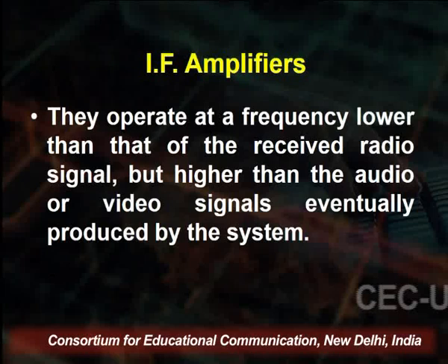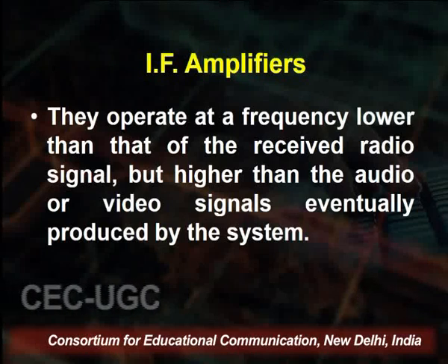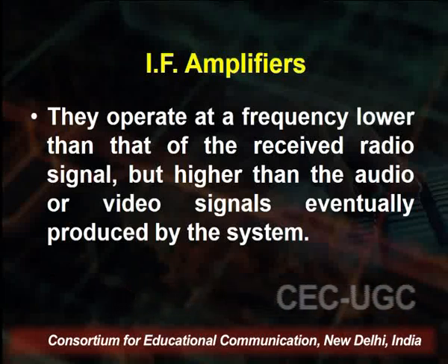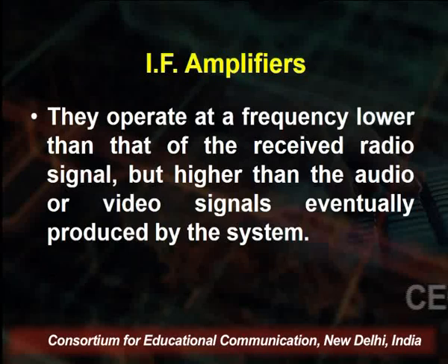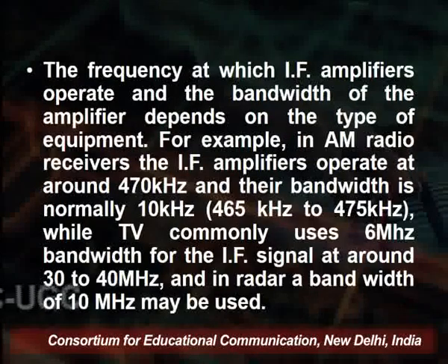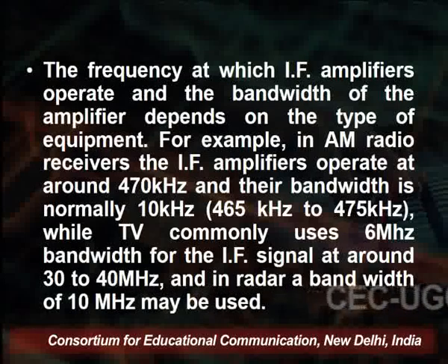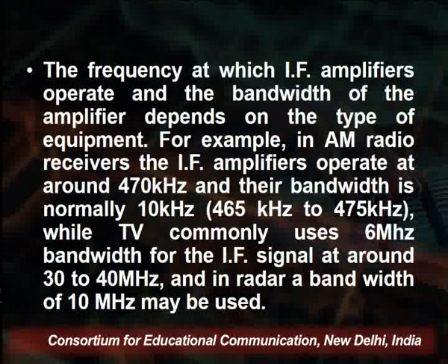So that's why it is an intermediate frequency amplifier that operates at a frequency lower than that of the received radio signal but higher than that of the audio signal. The frequency at which the IF amplifier operates and the bandwidth of the amplifier depend on the type of equipment used.